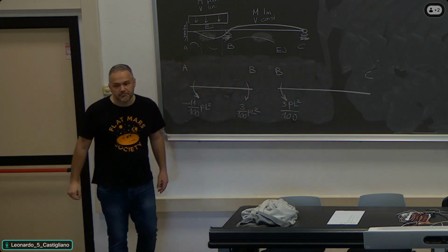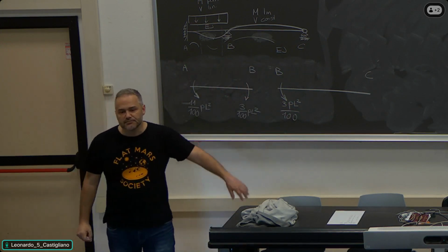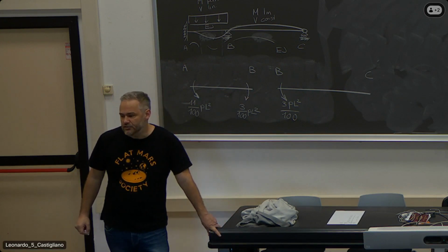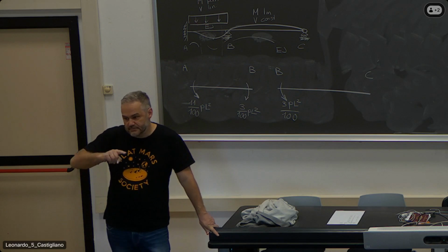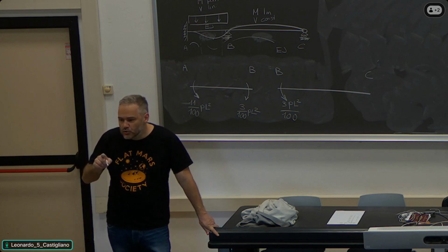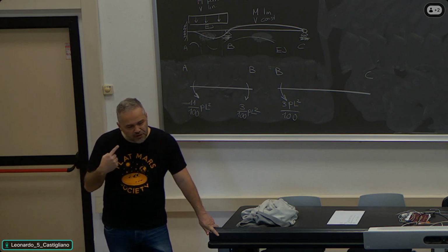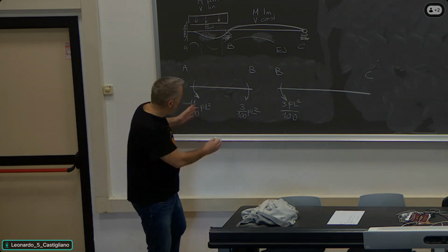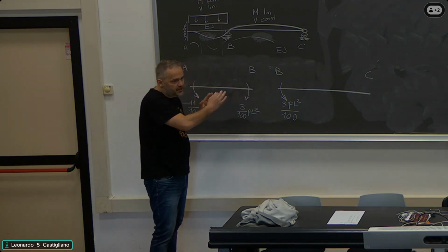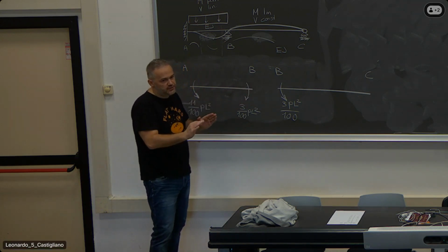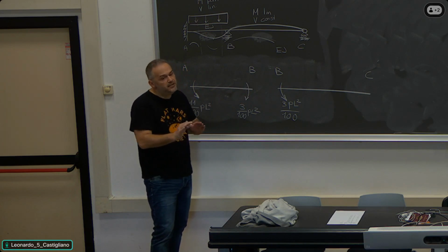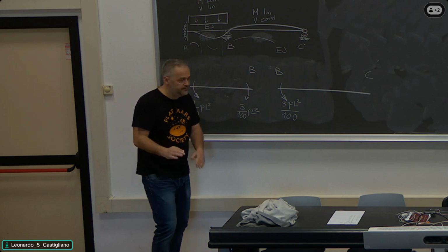That's the starting point, and that basically allows me to solve everything, because then what do I have? I have shear forces at the ends of the beams, and note, not what I'm saying, focus on my words. Shear forces, not restraint forces, okay? What I have on these two portions are shear forces. They may coincide with the restraint forces, they may not coincide with the restraint forces.